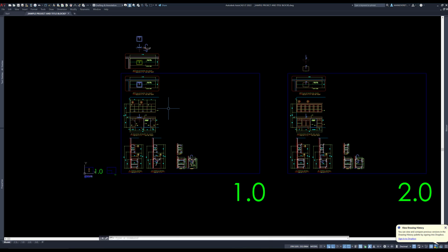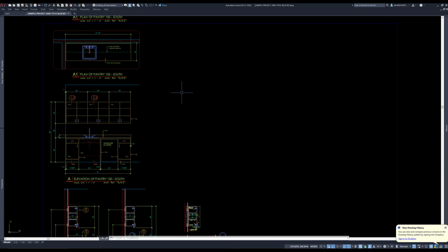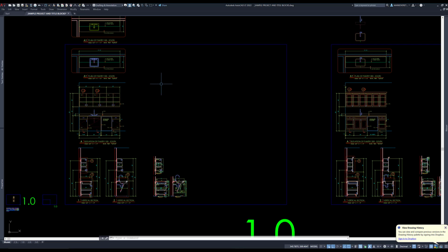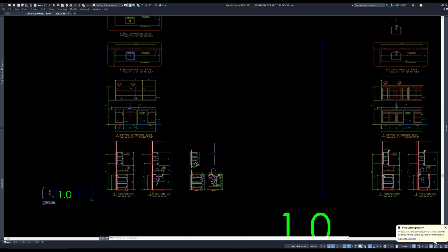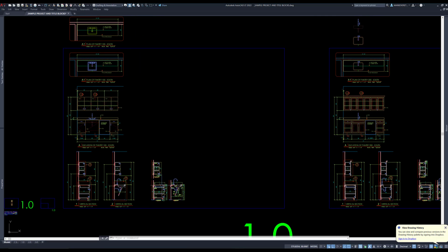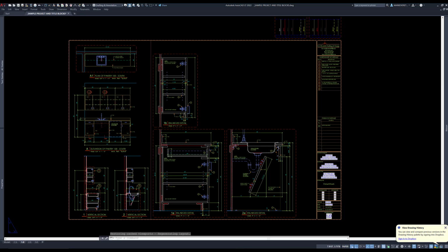So let's go over to the first drawing, and this is pretty much a standard, I'm going to call it typical, plastic laminate type job. I have a plan, an elevation, a couple of sections, and then some enlarged details. These areas of the drawing itself are pulled through a viewport. If I go back to model space here, it's at a 3/4 inch equals a foot scale, and then I further detail and enlarge those sections so that I can more accurately show all the dimensions and notations. These are too small to do that.